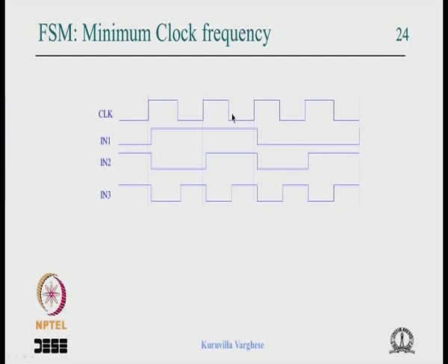Maybe we will make some output respond to this event, and that is how we control. Here again it is 1, then it is 0. So it is able to track all the changes in in1, and look at in2, absolutely no issue. When this clock edge comes, in2 is 1, then in2 is 0, then in2 is 1. No problem.